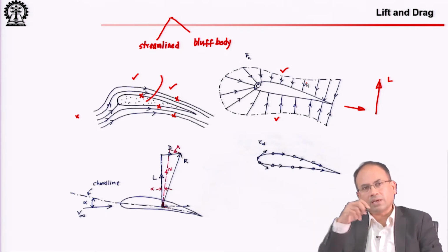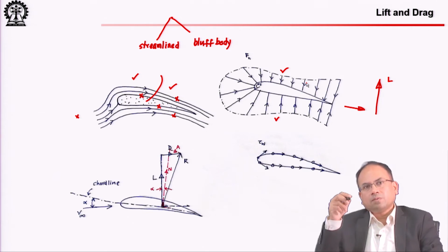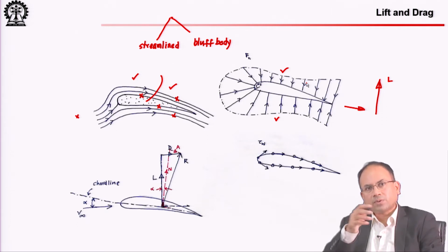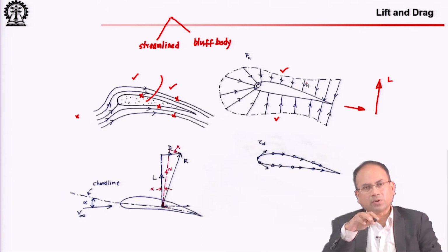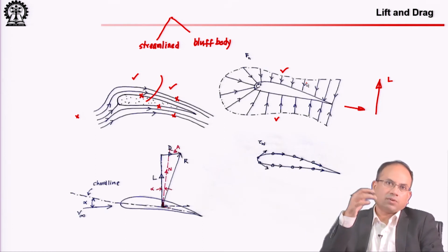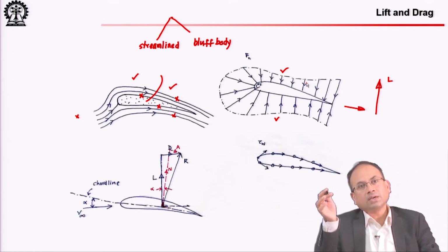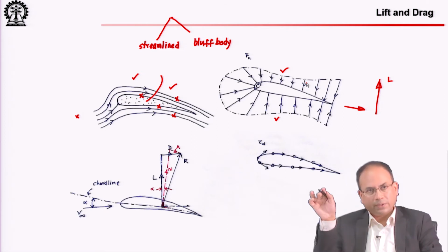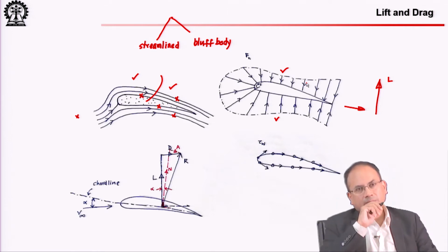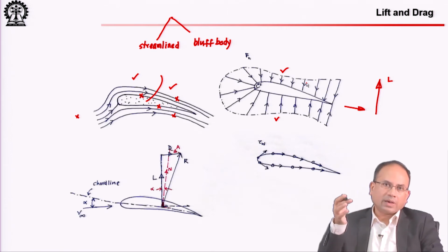However, in real life you get drag, and we will see that it really is from the boundary layer effect. We have not talked about boundary layer. After Bernoulli's theorem, we will get into the boundary layer phenomena, because to understand drag you need to understand the pressure distribution, hence the velocity distribution, but you also need to understand what is happening in the boundary of these objects. This was Prandtl's contribution, that because D'Alembert's analysis was showing that there will be no drag on these objects.